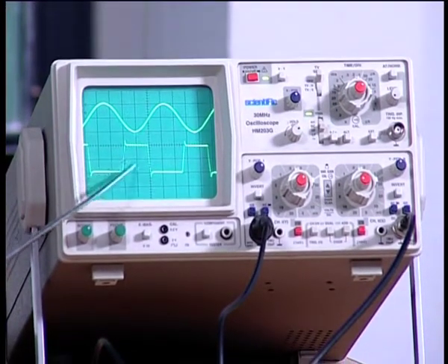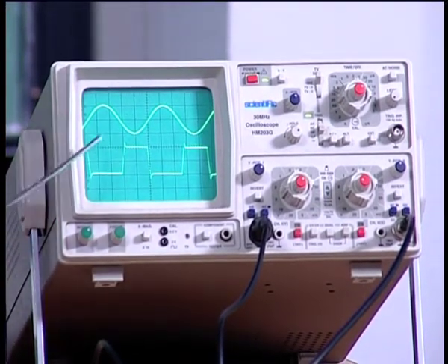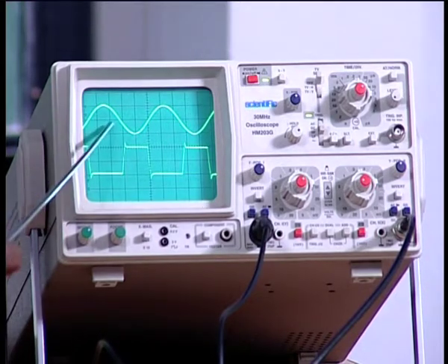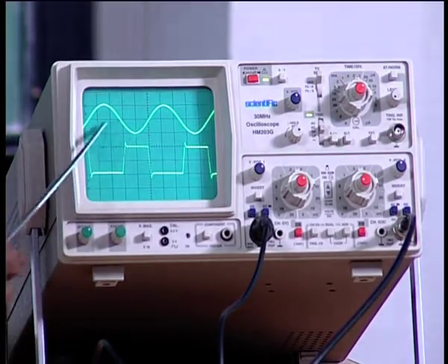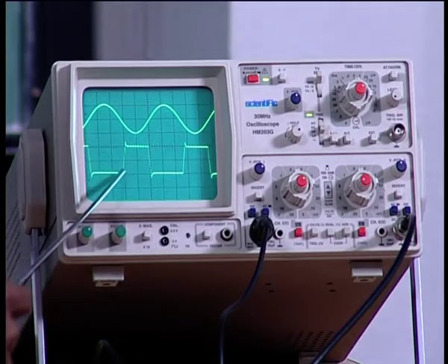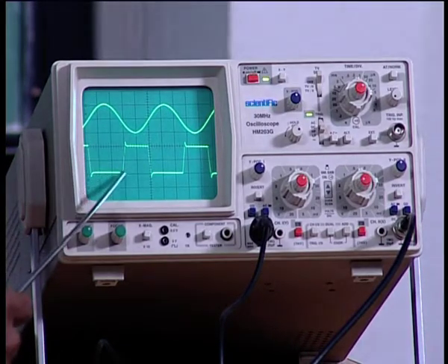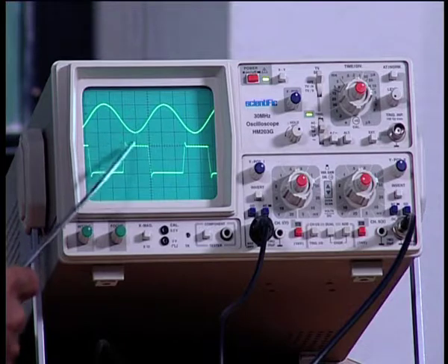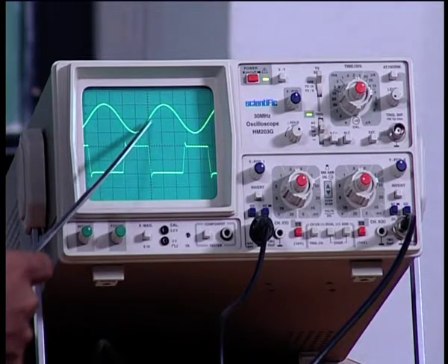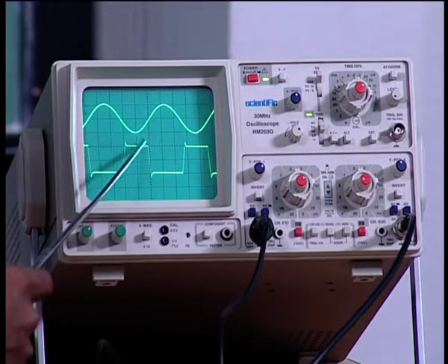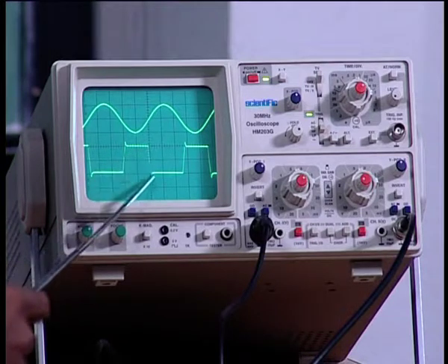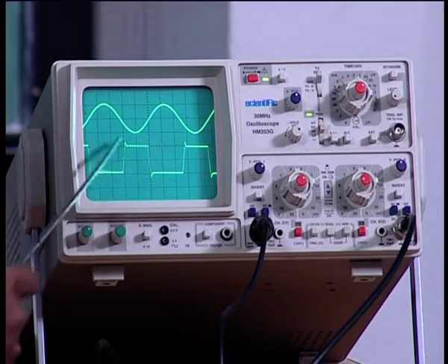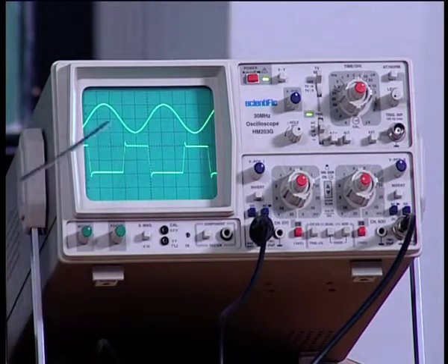This is the output. Now if you carefully observe, the 0 of the sine wave will be somewhere here, and so it has just slightly crossed that 0, immediately you find it goes to plus VCC on this side, and whenever this again crosses that point, it comes back to minus. These two are actually minus 15 and plus 15, or minus 12 and plus 12, something like that.